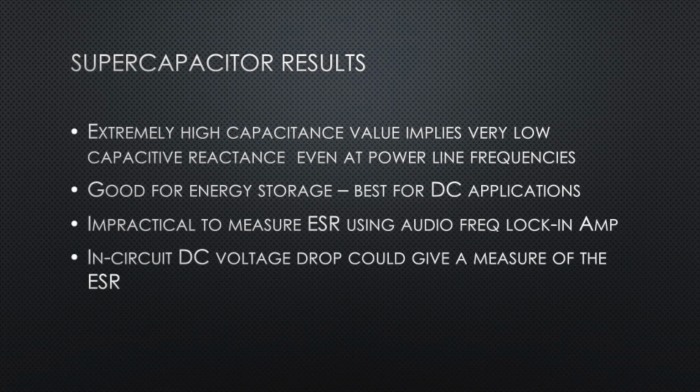So to summarize the supercap results, basically because of the extremely high capacitance, we got very low capacitive reactance even at power line frequencies like 50 Hertz, 60 Hertz. So I think these caps are good for energy storage, not meant for any AC filtering. It's impractical to really measure the ESR using an audio frequency lock-in amplifier.